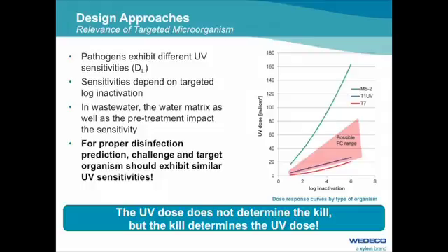And then on the other hand, it was also found that different pathogens exhibit different dose response behavior. So therefore, it is important to always associate the dose with a certain organism. Because there are some which are very sensitive to UV light, which are also all the coliforms. And then there are others which are a lot harder to destroy. And we today have the technologies to understand how sensitive an organism is, even from a specific water sample, and to design the UV system accordingly.